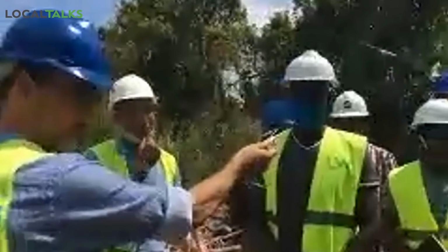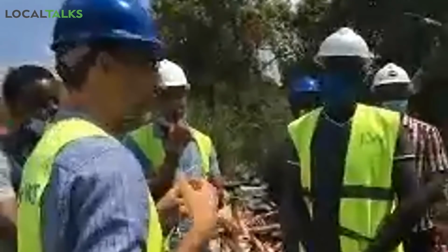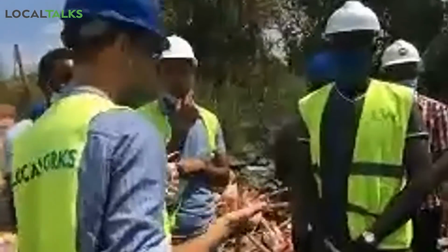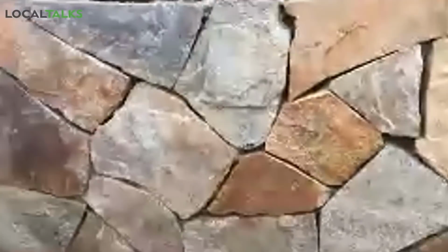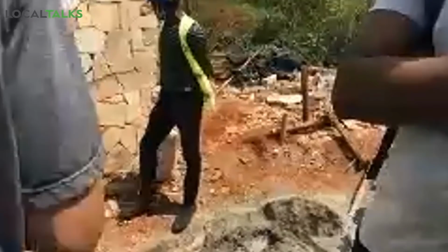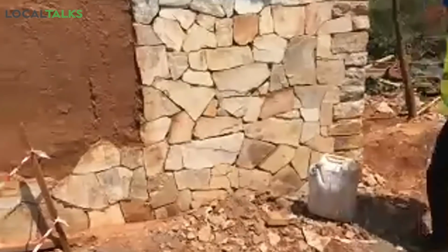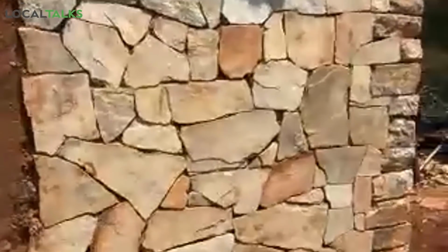Just the shallow ones. So essentially what we are trying to achieve is joints that are as small as possible. And in essence, what that requires is a lot of patience, because you need to find the right stone. You cannot just use whatever you find. I think this is a good example of a wall, where I hardly see any cut. I see one cut side there, but there are very few cut shapes. And we are very keen on that.